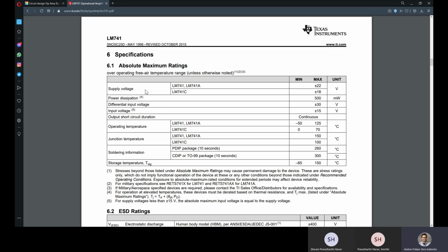And again, this is going to apply to transistors, to MOSFETs, even if you're working with Arduino. Arduino will have a datasheet where the specification tells you, this is how much current you can get out, this is how much voltage you can get out, and that's going to tell you, okay, this is where I need to be, so I don't burn my component. You don't want to fry it. So that's where you stay to be safe. I hope that answered your question.